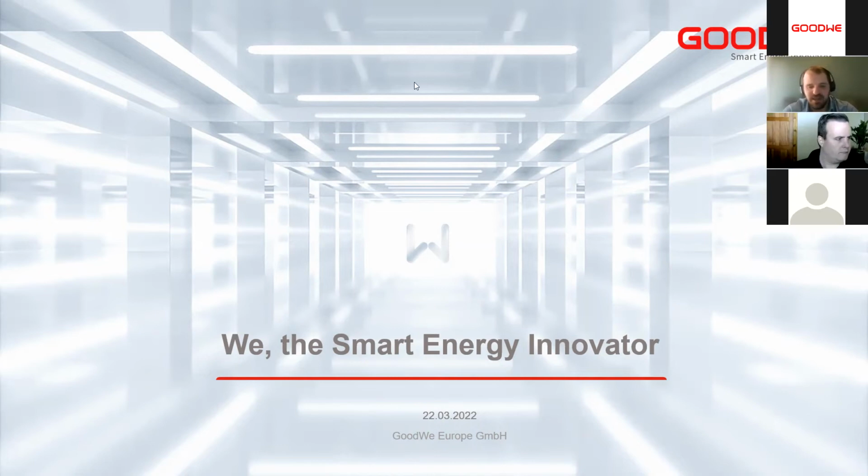It really depends on various factors, but I mean, the sweet spot in Southern Africa specifically is the 460 watt to 545 watt at the moment. We are seeing an uptake for larger power classes, for example, the 590 or the 600 watt. But with the larger power classes in the 590 to 650 range being a relatively new commercial product offering for the C&I space from JA Solar, we're still pushing the 166 and the 182 millimeter cells at this stage.